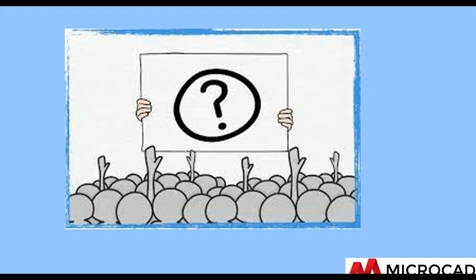Here's a question. Somebody wants to use AutoCAD as well. Of course you can use AutoCAD. There's plenty of projects where AutoCAD would be the design tool of choice. And absolutely, you can use AutoCAD files in BIM 360. You would be using the Autodesk Desktop Connector to map those files to the cloud files so you can work with AutoCAD just as if they were local. You just point to the Desktop Connector when you open the file instead of to your local drive system.